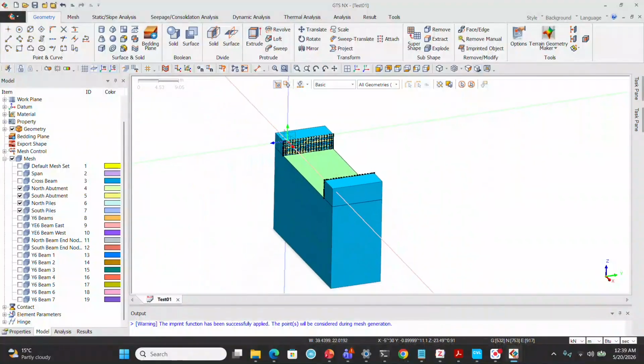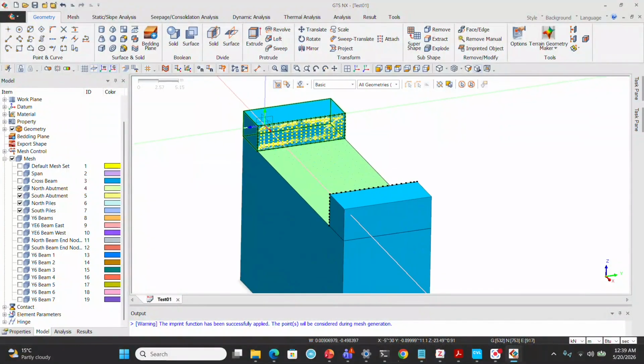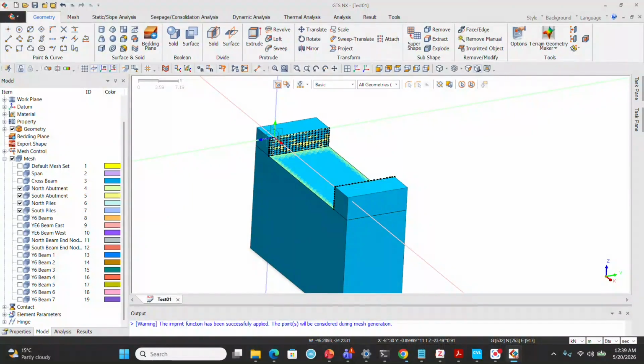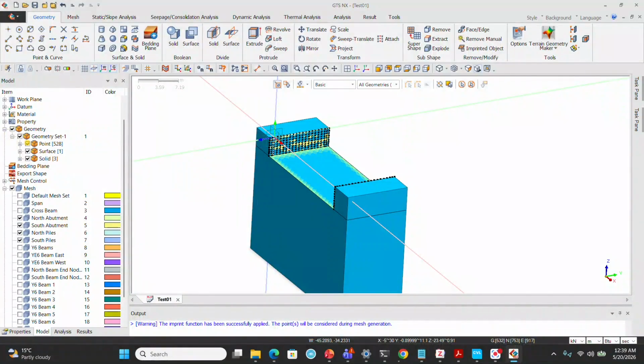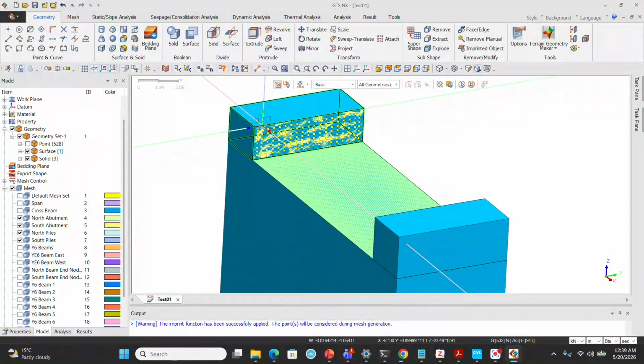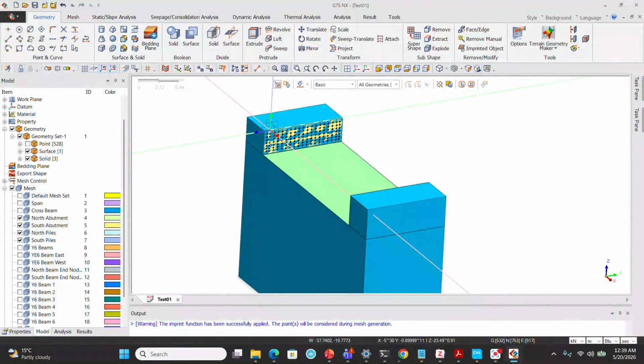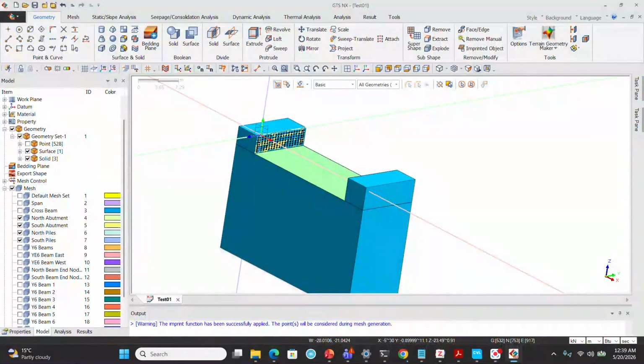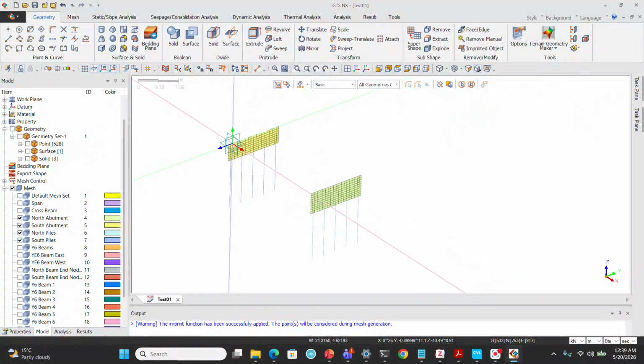So this will ensure that while performing the meshing operations, all the nodes for the 3D meshes are present where the nodes for the abutments have been imported. So the connections will be maintained. Now, even if you switch off the original geometry points, you can see that the points already exist on the 3D geometry. That means the imprint has worked. Okay, now let us go back to our model without the geometry.